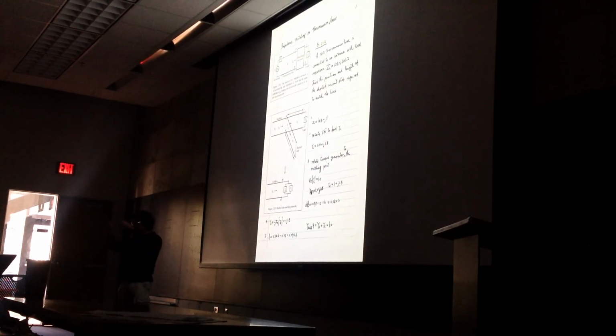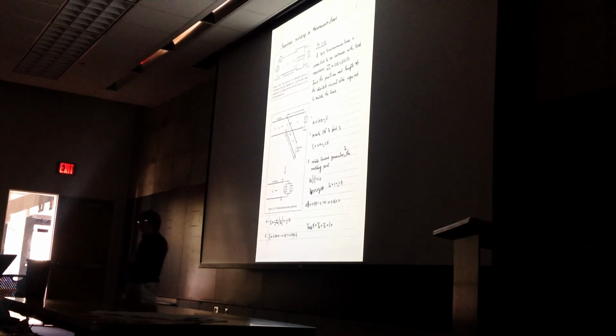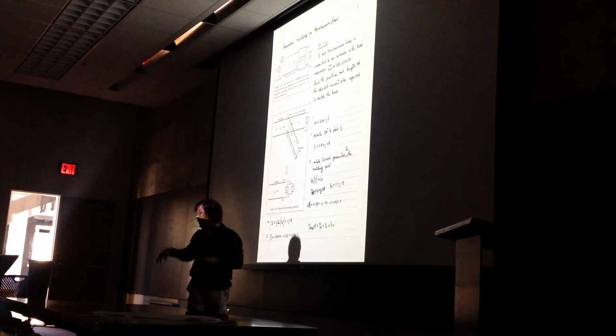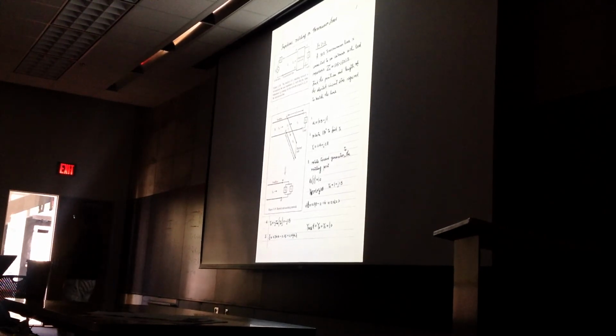If you put in a lumped inductor L right there, that L may behave differently. When you connect to it, it will already have a capacitive effect. Second, it is only like an inductance at a particular frequency. So if you go to a different frequency and still use the same inductance, your gamma will actually be bigger than using a transmission line. So this is a better technique to get wide band operation. So in a physical sense, you're just attaching another wire.